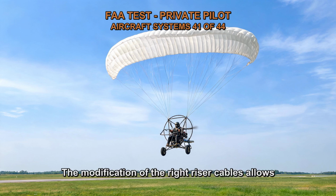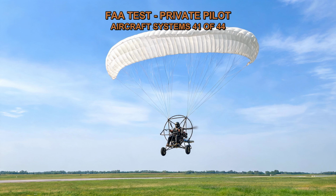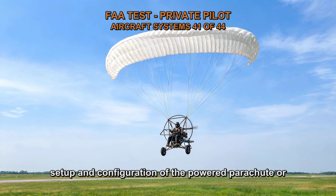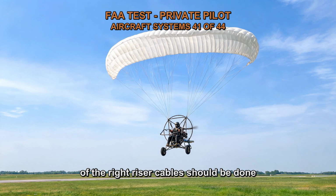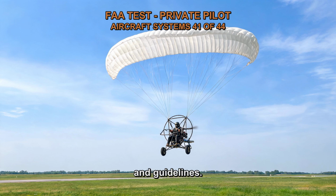The modification of the right riser cables allows for precise control over the lift distribution and helps counterbalance the rotational forces generated by the engine. This adjustment is typically made during the initial setup and configuration of the powered parachute or when flight characteristics need to be fine-tuned. It is important to note that the adjustment of the right riser cables should be done carefully and in accordance with the manufacturer's instructions and guidelines.